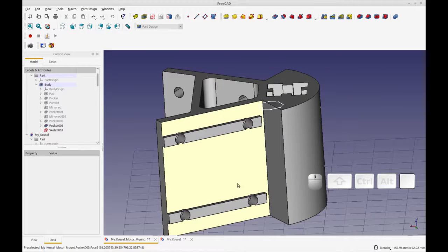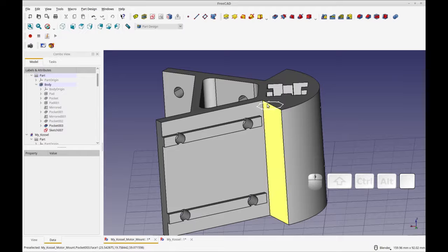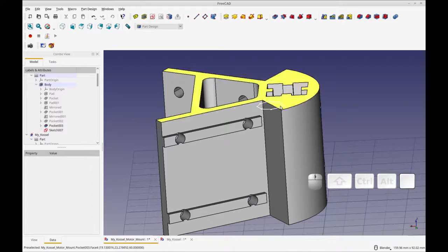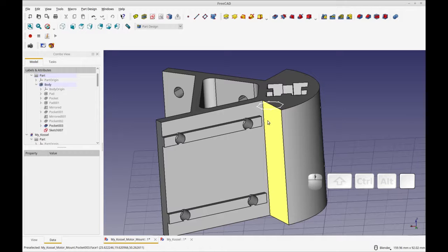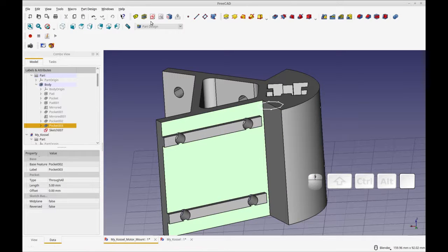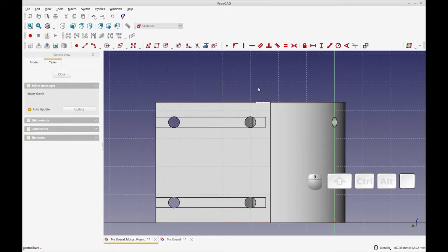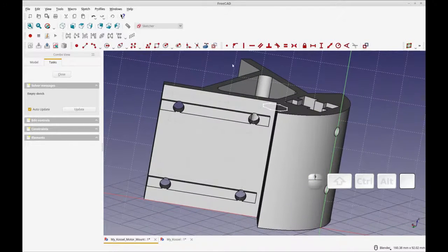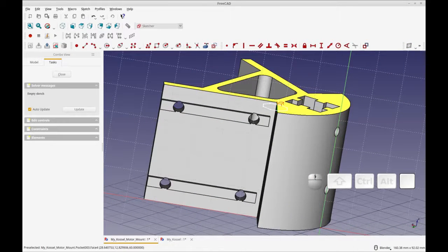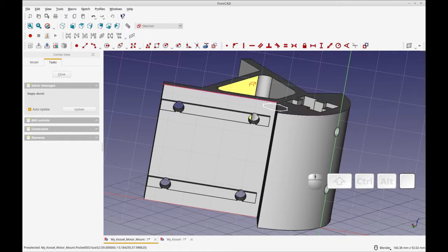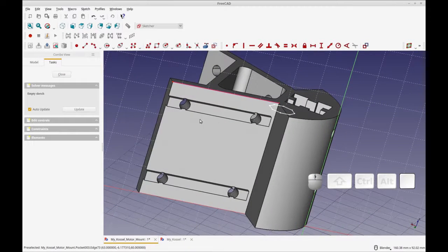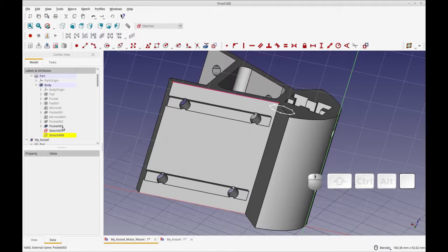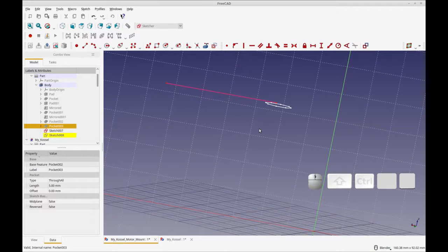The next step is to create the sweep path for this sketch. So this sketch is going to be swept down from this face into the body to this face. So we're going to put a sketch for that right here. So there's our sketch plane, and the external geometry we're going to need for that is not this edge, but we're going to need that point, and we will need this edge. So with the external geometry selected, I got that point from this geometry, so it just canceled that one out. So with that selected, I'm going to hide the body.